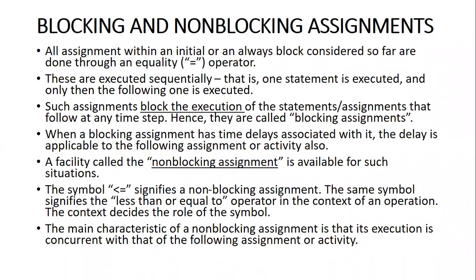Such assignments block the execution of the subsequent steps. The first line will be executed, then we go to the second line, then the third line. It is not that the first, second and third lines are all executed at the same time. Hence they are known as blocking assignments.